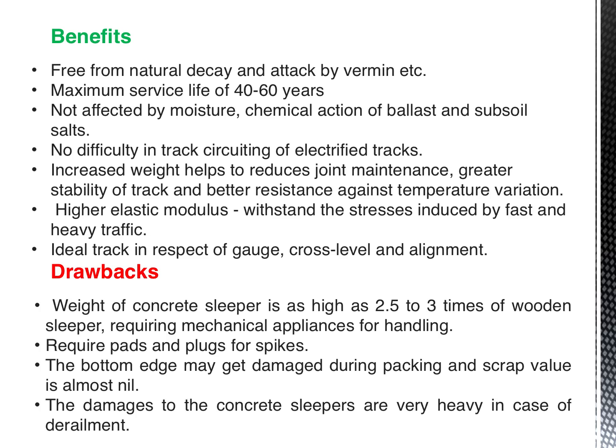But wood and metal sleepers both have very good scrap value, while concrete doesn't have any; the depreciation cost is zero. And the damage to concrete sleepers is very heavy in case of derailment, and it may require frequent change of the concrete sleepers. Okay, so these are the benefits and the drawbacks of using the various types of railway sleepers in the construction of the